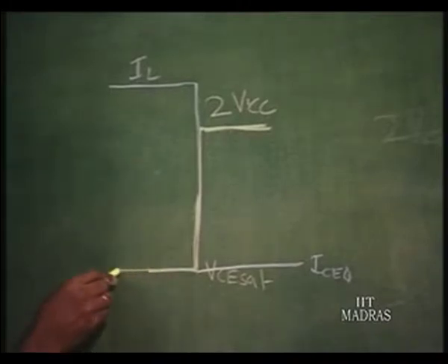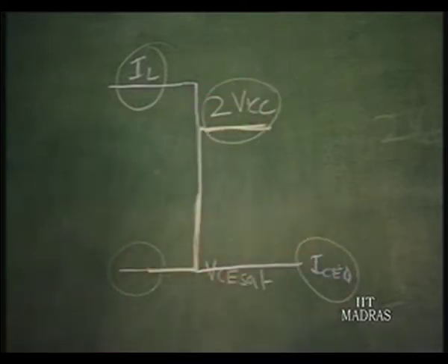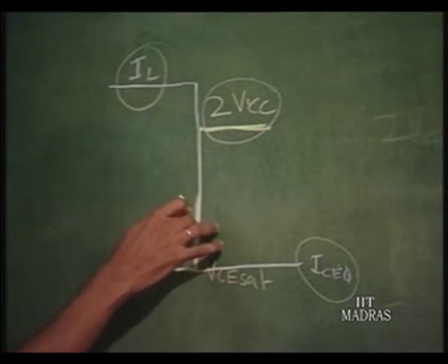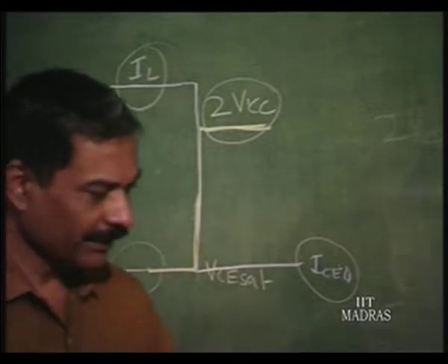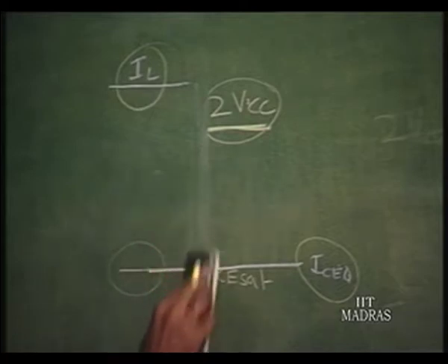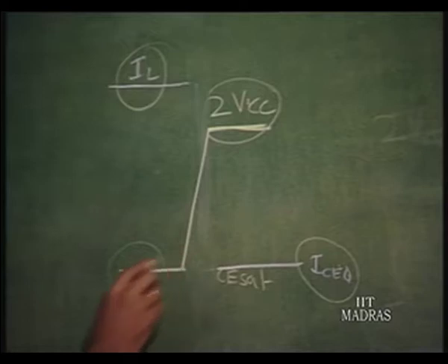So, we have already established the power that is spent here as well as here for the transistor. But this assumes that it takes almost 0 time for it to go from off to on. When you are working at very high frequencies, this time for it to go from off to on is not negligible, so it becomes comparable to the time period.